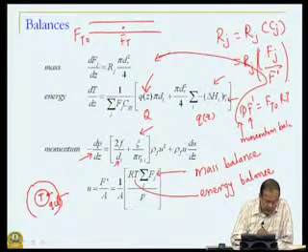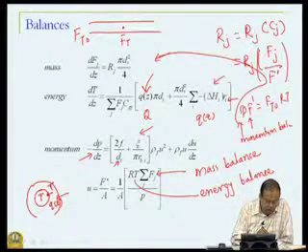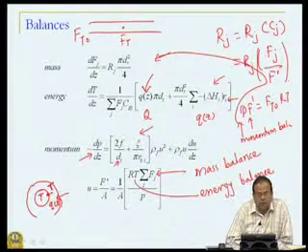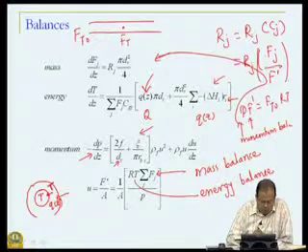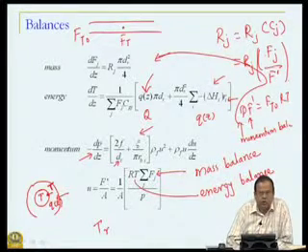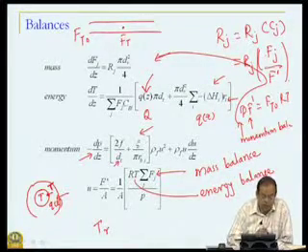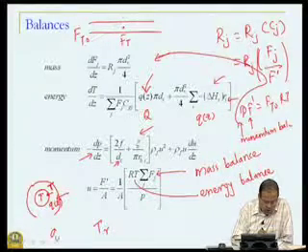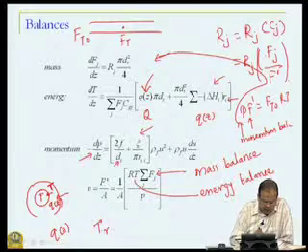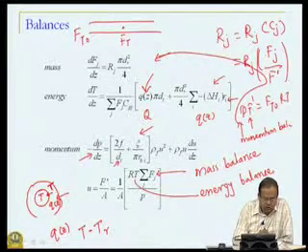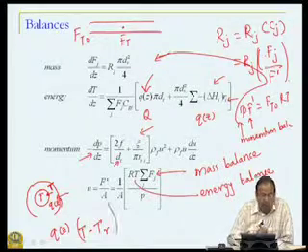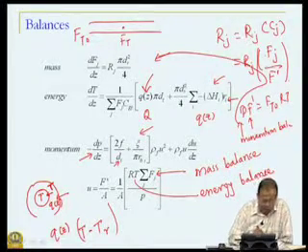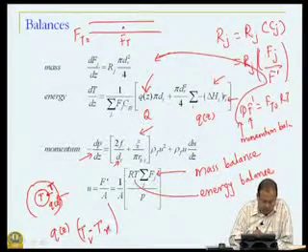I can express it in terms of the temperature of the flue gases that I am passing through. So, I can bring in the reference temperature TR, which again will change along the length of the reactor, but this Q of Z is then related to the temperature difference between inside the tube and outside the tube, TR minus T.